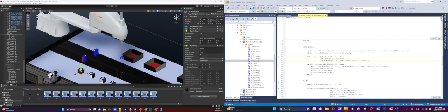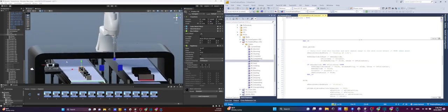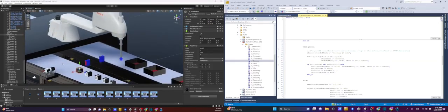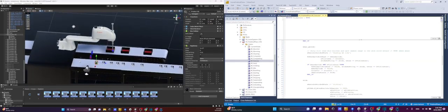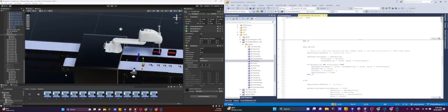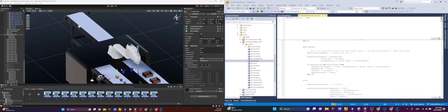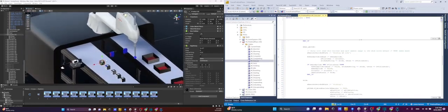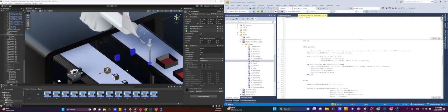First, if I can't read the QR code, I want the product to continue on the conveyor, and it will eventually be conveyed out of it. At the end of it, we will have a reject bin, and the product will fall into that reject bin. And the second thing that I want to do is tell the operator, tell the log, that I could not read that barcode.